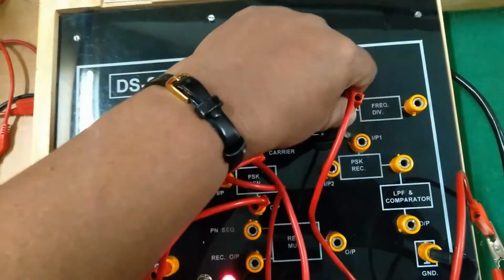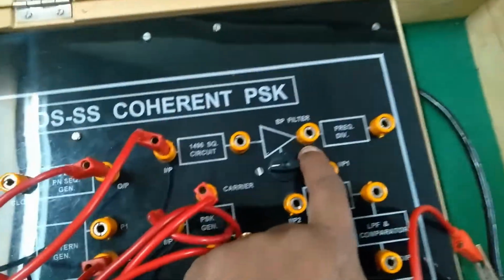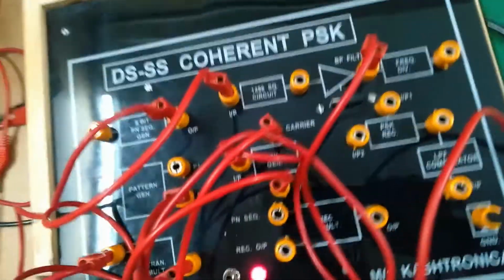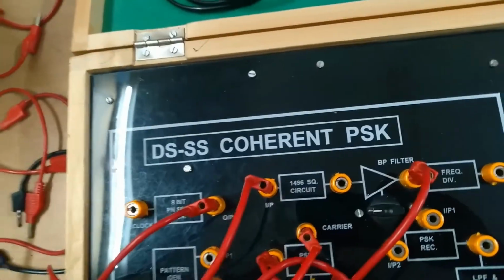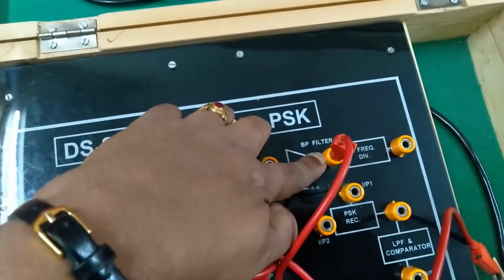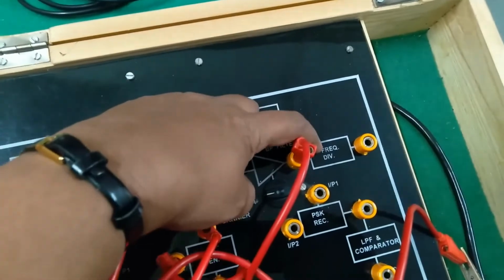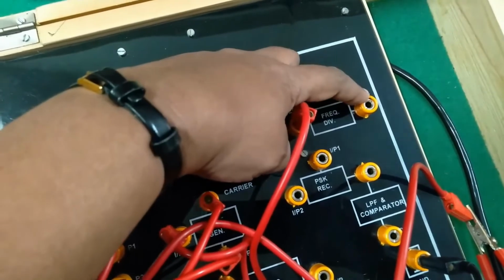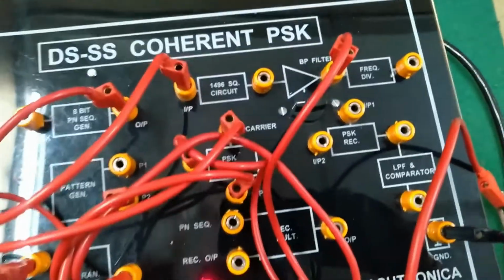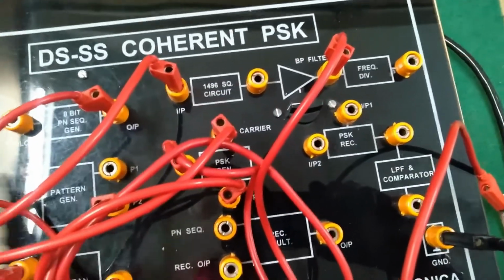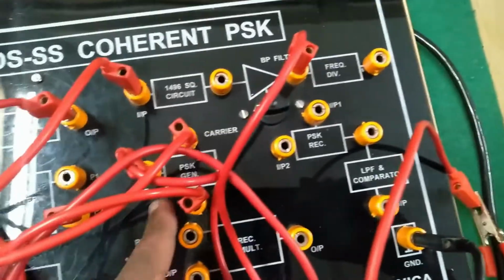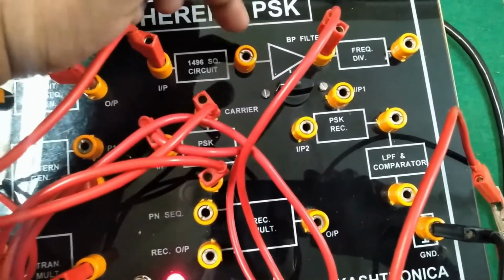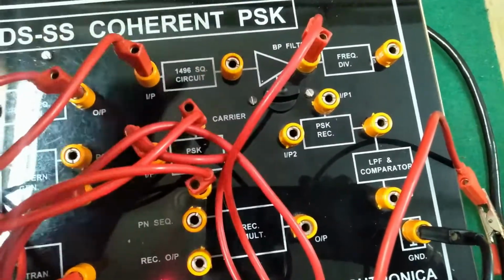Now what you can see is this is the band pass filter output, which is twice omega ct. It is divided by 2 now. So here I get once again my carrier back, that is omega ct. So what you have done is, at the receiver end, you have generated the carrier back again from the transmitted carrier by using this particular circuit, which we call a carrier recovery circuit.